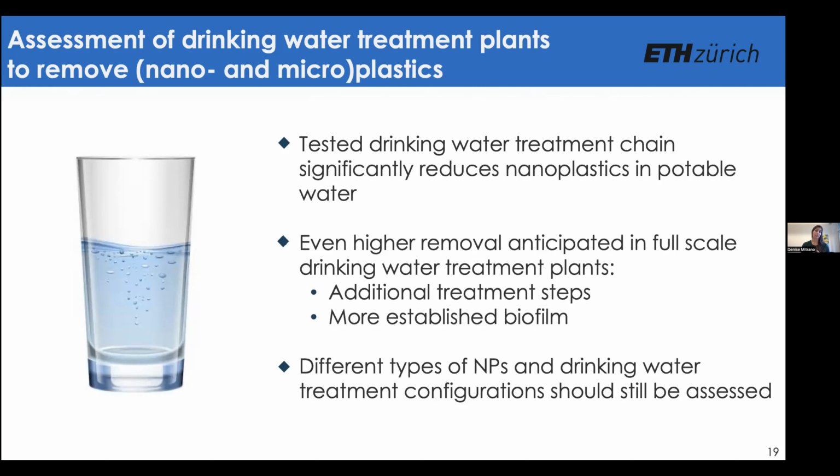So this slow sand filtration step, for example, is now often not being included in a lot of new drinking water treatment plants because it takes up a lot of space physically, and it's also more expensive to operate. And so it's also quite important to be able to see how this is going to affect different types of drinking water treatment plants in the future.